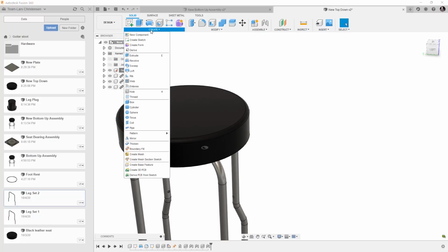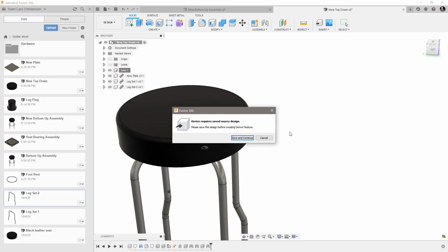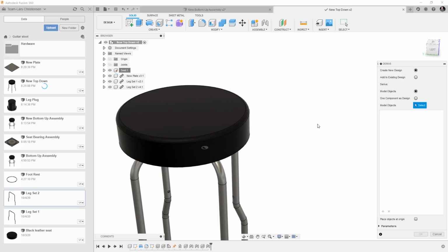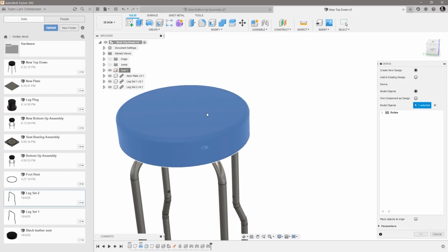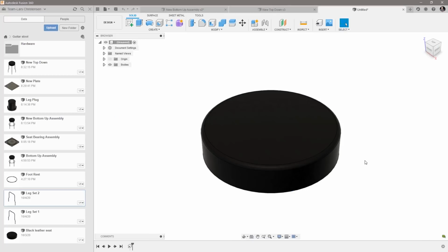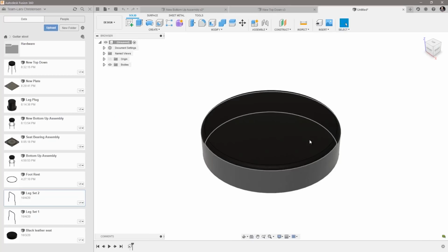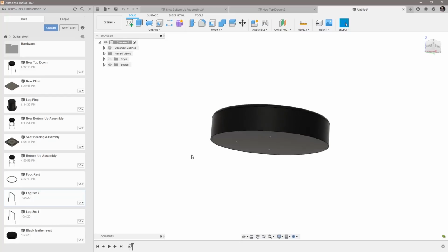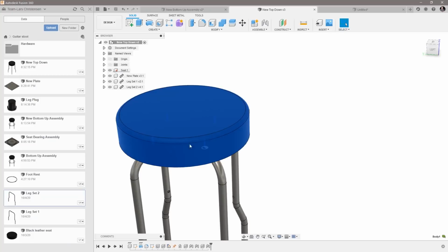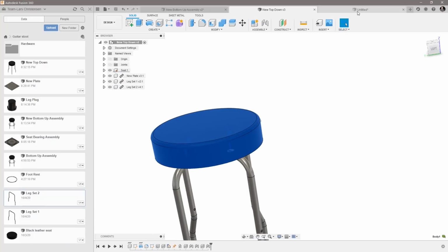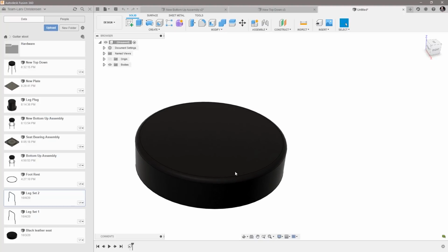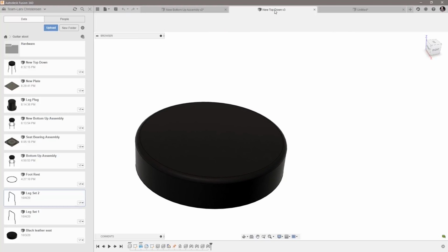So it's sitting under Create. So I'm going to go ahead here and say that I want to create a derived. I'm just going to save here. And I want to use the seat as my derived. So I'm going to hit OK to that. That's going to open up a new file; it made a copy of that original seat. It's linked from our original assembly here to the new file, but anything we're doing in this file will not affect what is in this file.